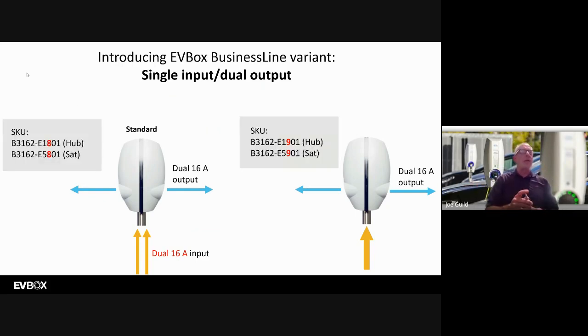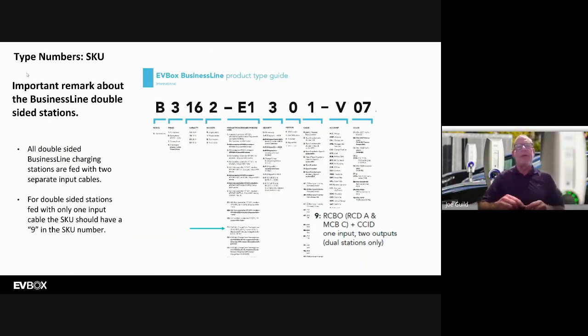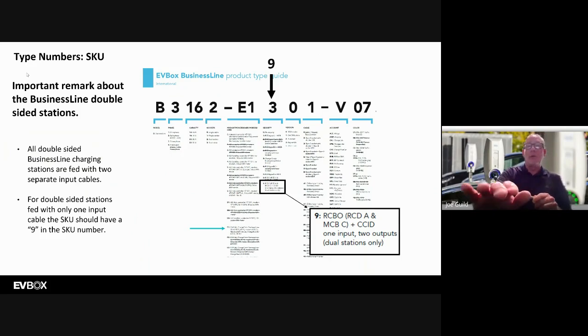This has to do with the part number. And again, you'll have these slides, but it's important that we know. We notice that this gets overlooked a lot. If it's a 9 after the E1, that means it has that 1 cable. And if it's an 8, that means it's the standard version of 2 cables in there like that. And I don't show that. I had another slide where you see that that's protected. Of course, this one has a 32 amp breaker in here, and this one 2 16. So we can't mess those around and switch them like that, just so you know. Very good to know. And this is just showing where that is. That number here should be a 9 or an 8, depending on what it is.